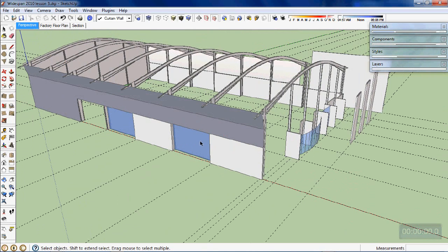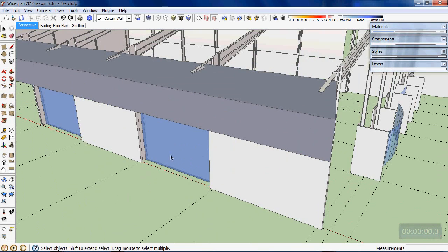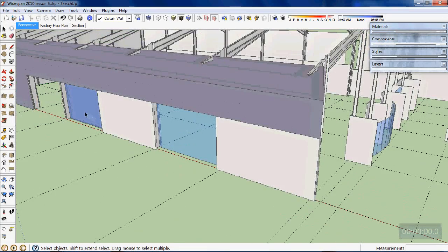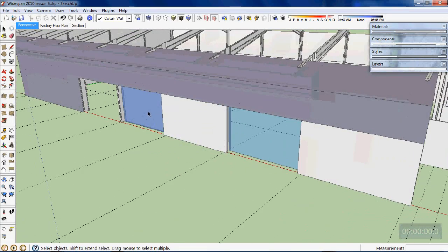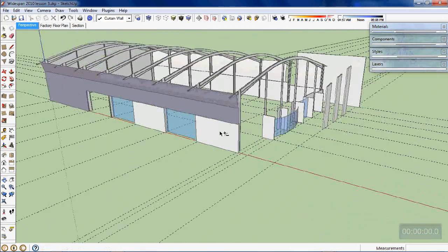If you triple click on that glass curtain wall, triple click again, so I've picked up the whole component at the moment. What I need to do is hold my shift key down and double click on the front face. The reason why, I'll just delete that now to make sure, and yes, I've kept that front face there now. Just to show you that again, triple click, then shift key and double click, and then delete. Press the delete on your keyboard. Do that to all the others.